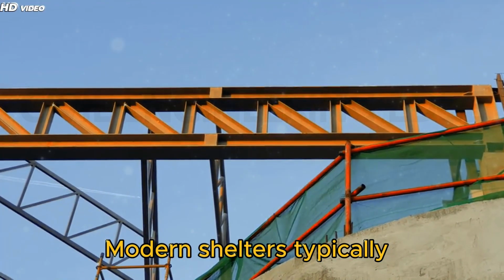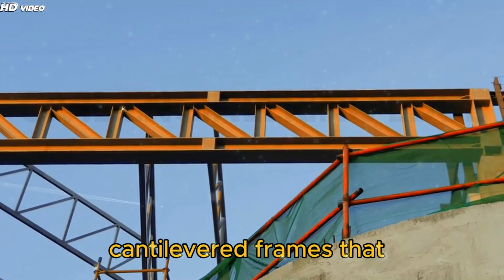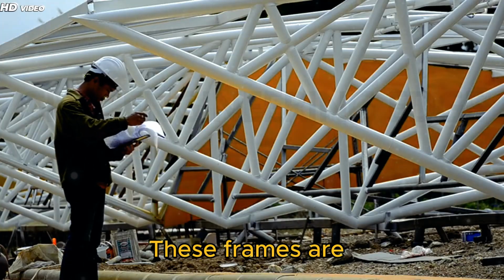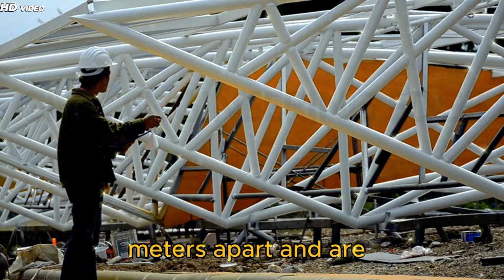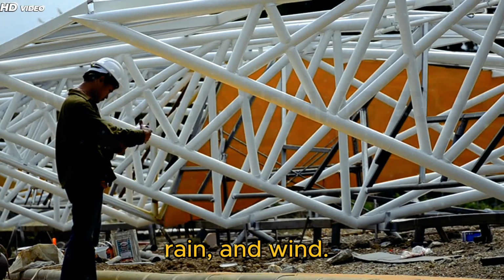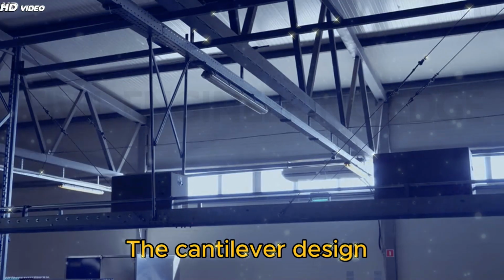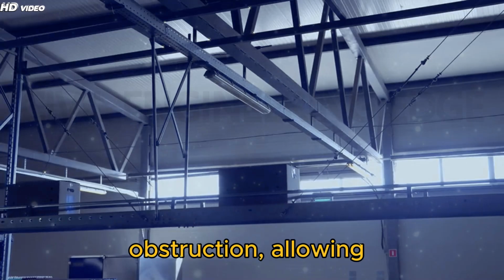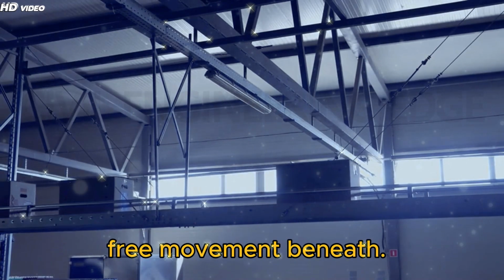Modern shelters typically consist of precast cantilevered frames that support a lightweight slab. These frames are spaced at 2.5 to 4 meters apart and are engineered to provide shelter from sun, rain, and wind. The cantilever design ensures maximum space utilization and minimum obstruction, allowing free movement beneath.